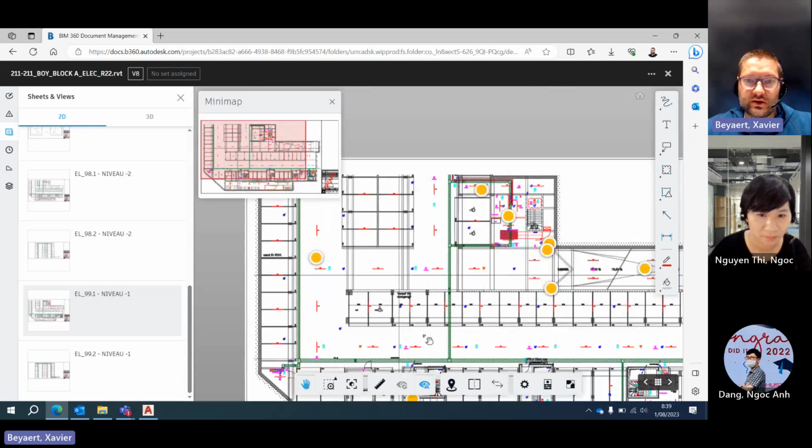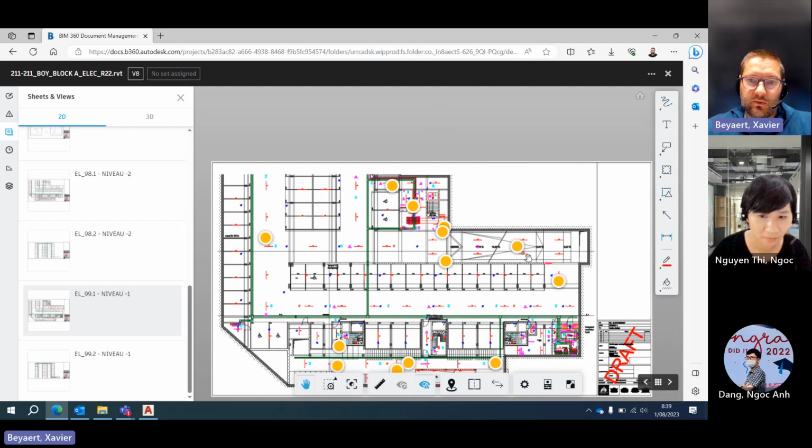So what I do mostly is, we use two or three circuits for the parking area, maximum 30 light fixtures per departure. So if you have a departure of 10 amps, you place a max of 30 light fixtures behind it.